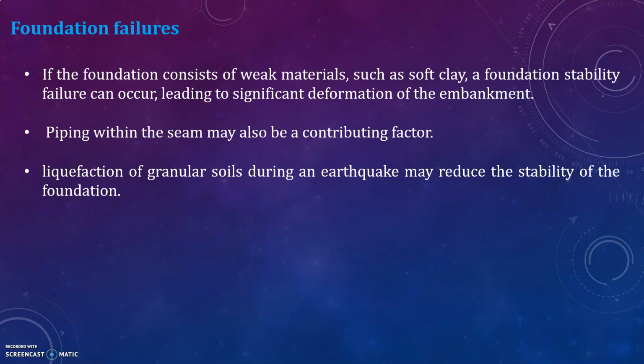That is, maybe the foundation consists of weak materials, soft clay, etc. And piping within the seam may also be a contributing factor, and liquefaction of granular soils during an earthquake may reduce the stability of the foundation. So these are some of the common reasons for the failure of the dam.